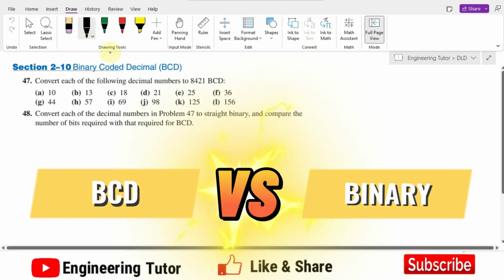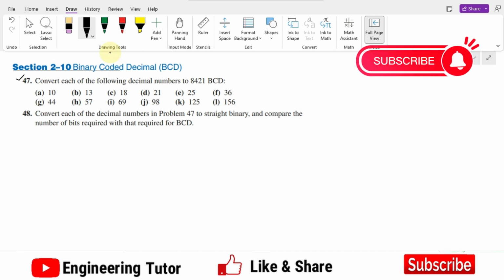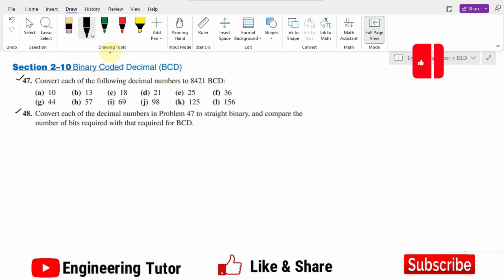Welcome back, guys. So this is a very interesting question. We have previously solved question number 47, in which we have converted each of the numbers here to their BCD equivalent. In question 48, we are asked to convert each of the decimal numbers in problem 47 to straight binary, and compare the number of bits required with that required for the BCD.